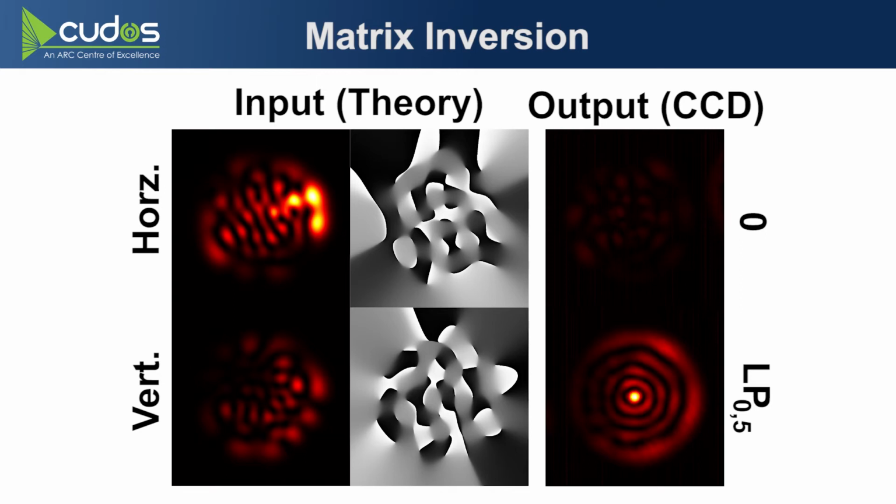Given the measured mode transfer matrix, I know that I must launch this mixture of amplitude, phase, and polarization at the transmitter. That's a simulated image. There's no observation camera at the transmitter. So you display masks on the transmitter SLM designed to generate those fields. And this image is observed on the polarization diverse imaging system I've got attached to the receiver.